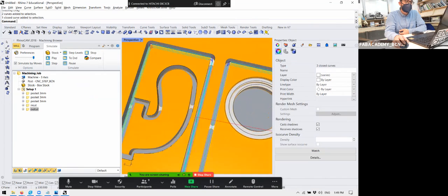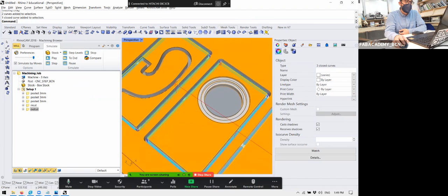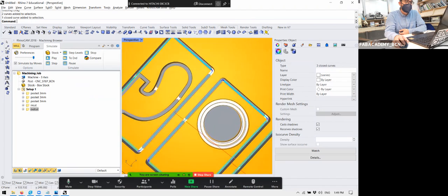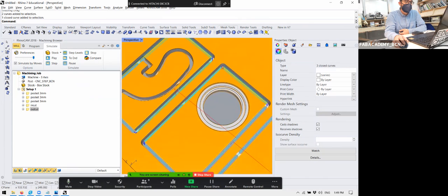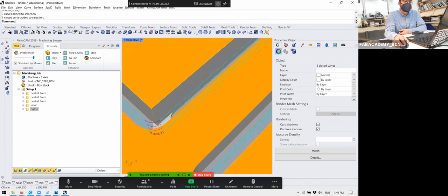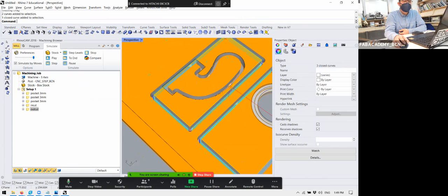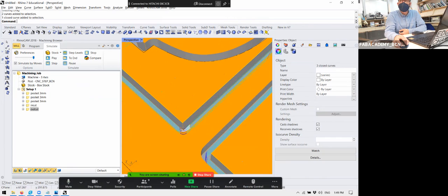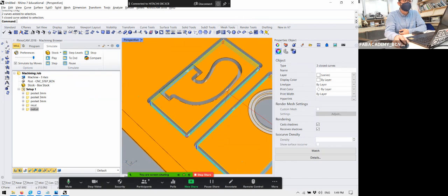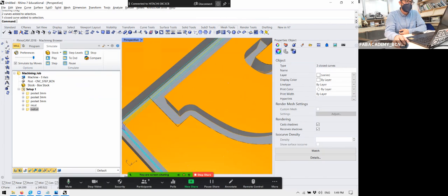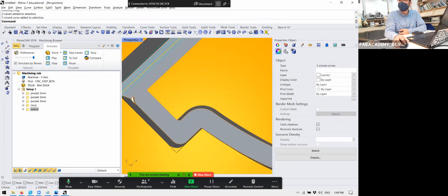It's like the dent of the boxes in and that's if you rub it. If you want them to be straight, you have to change the path. Look, but the part that I want is this one. It's straight. Well, it's the interior ones that are not straight. For example, here, you see, this we don't want. In that case, we need to add the dog bone, the T-bone, and we need to do it manually. This is on the design. It needs to be in the vector. And that's the annoying part.